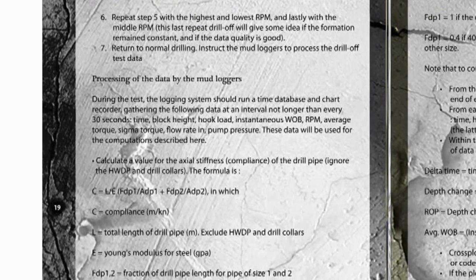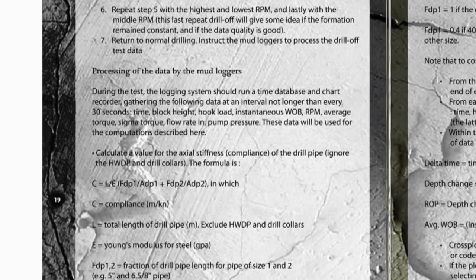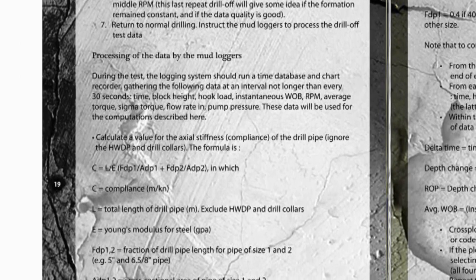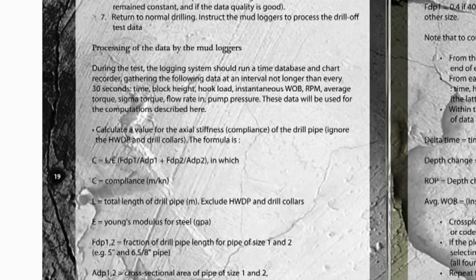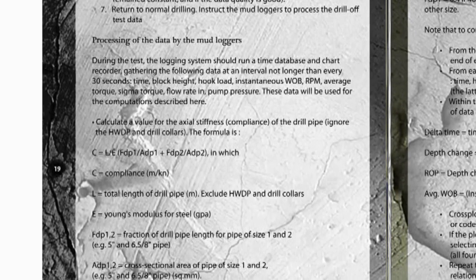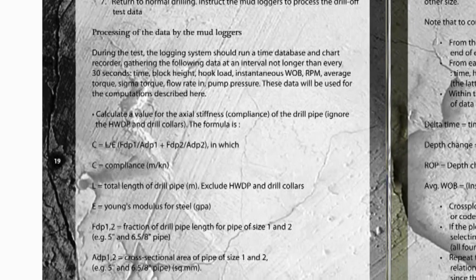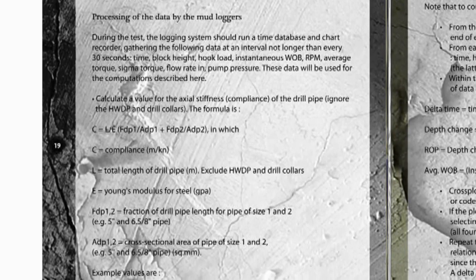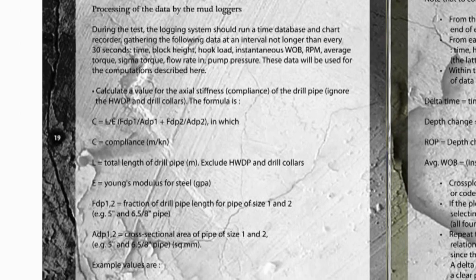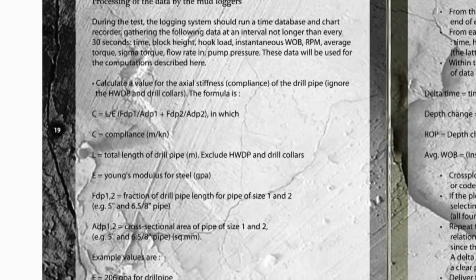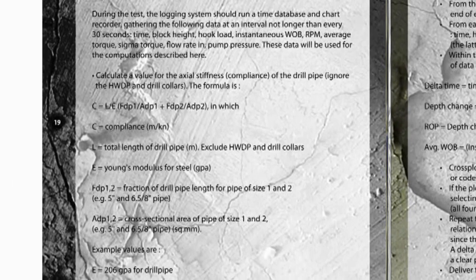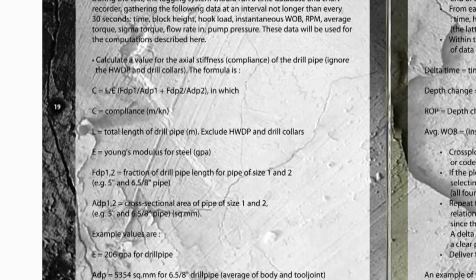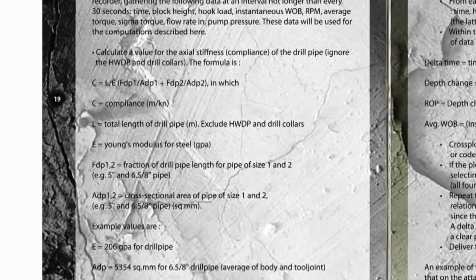7. Return to normal drilling. Instruct the mud loggers to process the drill-off test data. Processing of the data by the mud loggers. During the test, the logging system should run a time database and chart recorder, gathering the following data at an interval not longer than every 30 seconds. Time, block height, hook load, instantaneous WOB, RPM, average torque, sigma torque, flow rate in, pump pressure. These data will be used for the computations described here.